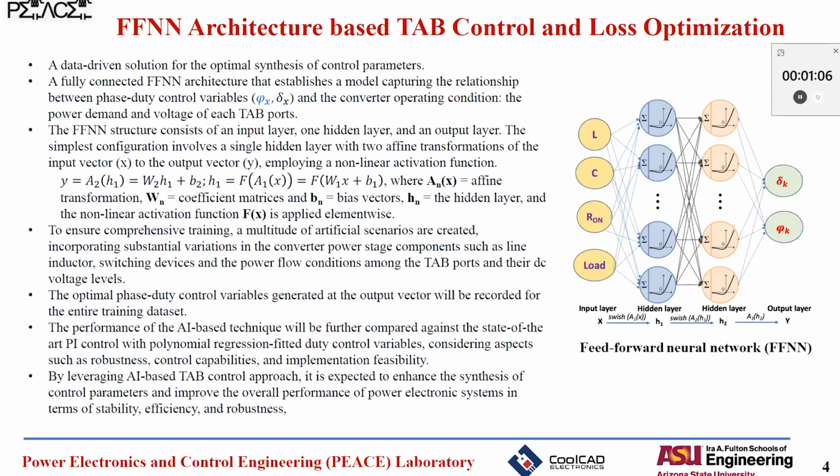So in this case, we are executing the converter level control in the DSP, and the feed-forward neural network, this machine learning algorithm, is run in the FPGA as a side channel operation, while we establish inter-controller communication for data exchange. And these AI methods are much superior compared to the conventional lookup table based approach that is deemed a very memory intensive solution with a higher space complexity. Next slide, please.